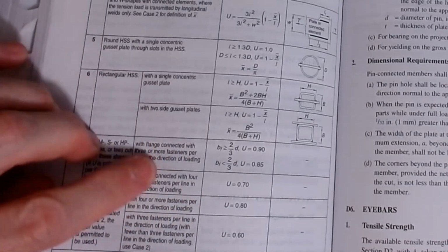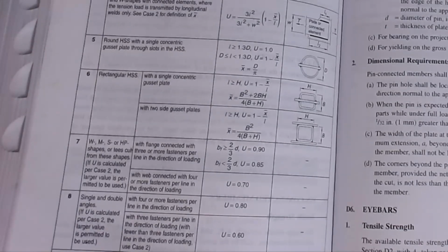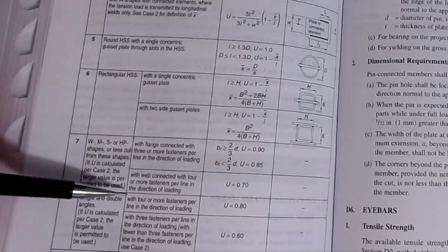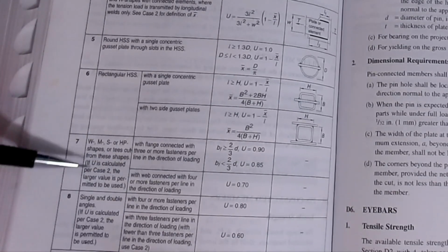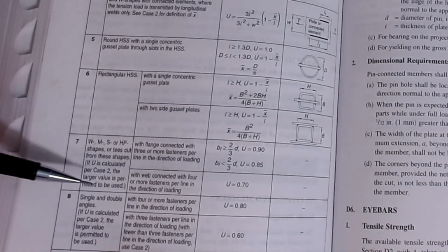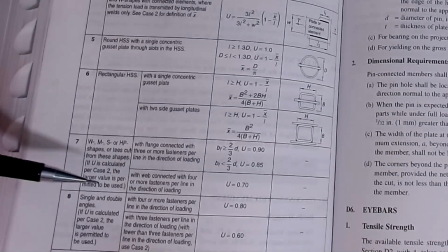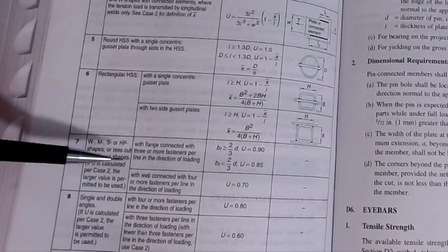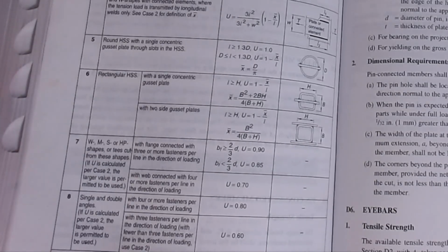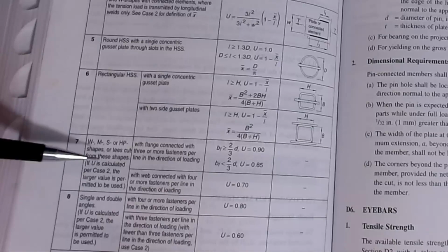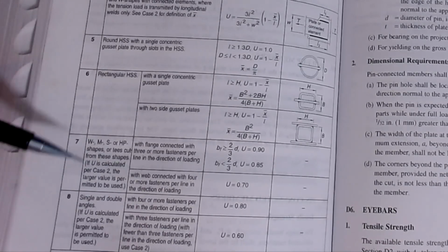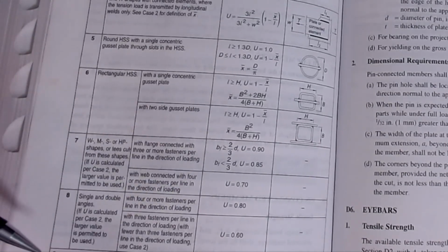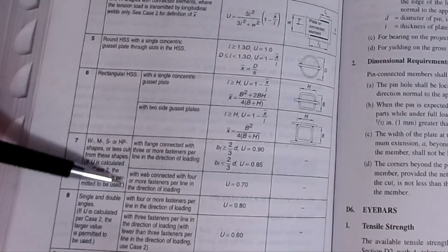So this is why those 2 rules exist, so that I can take some first guesses. Typically, as you can see, bolting the flanges gives you a stronger connection for net fracture than bolting the web does. Now, as we're talking about this, recognize that we're only looking at the net fracture case. We're not considering other phenomena like block shear or bearing, because as you'll see in the videos when we get to those, we have more control over that layout about spacing. I'm just looking to see, can I get these bolts laid in a certain fashion, and where can I put them, and what maximizes my U value, because this will result in a smaller member size. So that's why we're looking at flanges or webs and answering that question right off the bat.